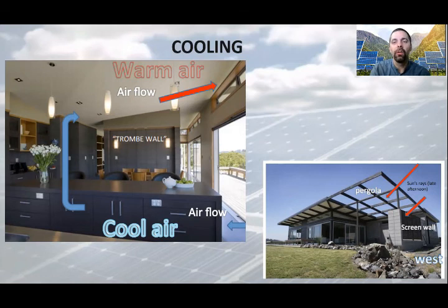This means warm air will rise and follow the slanted ceiling, and the warm stale air will escape through the ventilation windows. This will stimulate passive ventilation in the building and create an assisted movement of the air. Cooler air will now flow in from the bottom, creating a constant flow of cooler fresh air during summer.